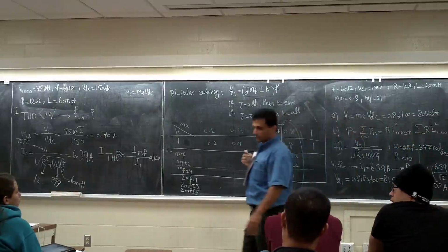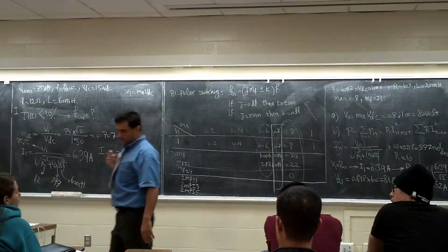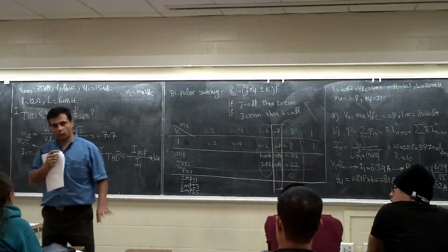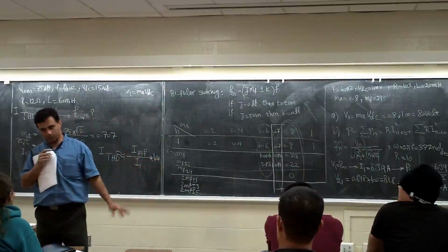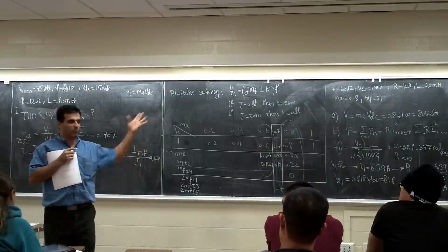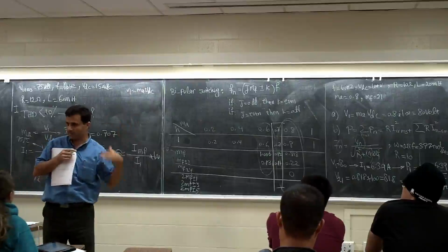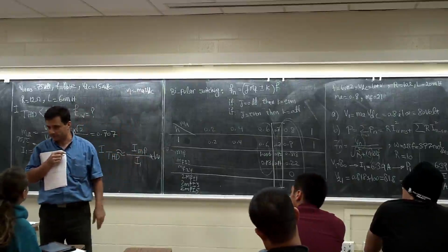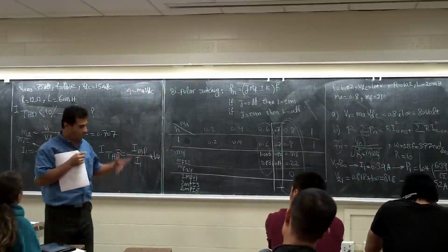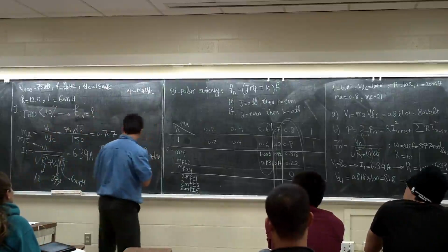Can we just use it, like the requirement is 10%? Let's set it 8%. No, I'm going to compensate it another way. Hold on, you can do the compensation. Whatever you select later, you should go back, like the previous example, and solve it again to make sure your THD is less than what they asked. Double check that. But the way we are going to do it is going to be definitely less than that.